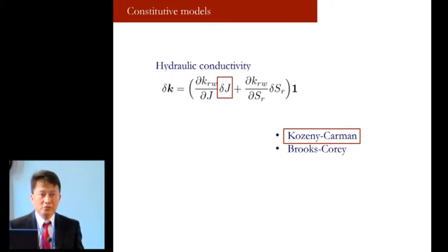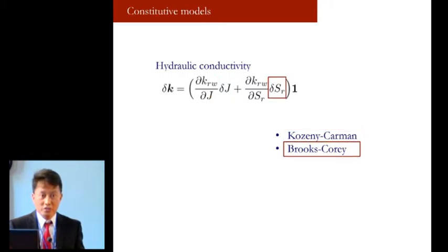For example, the Kozeny-Carman constitutive law for the hydraulic conductivity tells us that the hydraulic conductivity varies with the porosity of the material. The Brooks-Corey relation, very commonly used in hydraulics, tells us that the hydraulic conductivity is also a function of the degree of saturation. So clearly, we have a UP formulation.